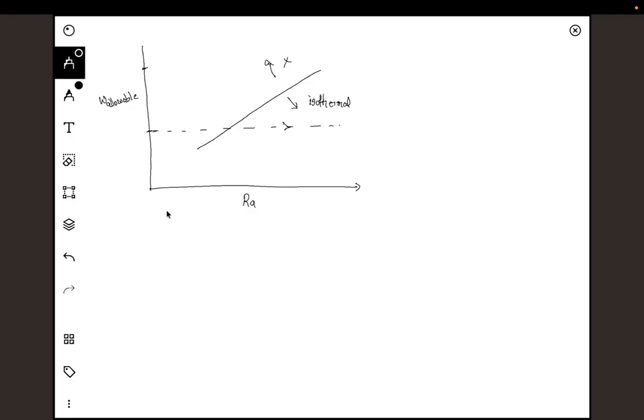But for example, the glass panes inside a window are like 4 mm, 5 mm, 10 mm, which is very small compared to this range of Rayleigh numbers. So you can assume that the entire glass pane is isothermal, and use the correlations for isothermal instead of heat flux or any other non-uniform temperature variation across the surface.